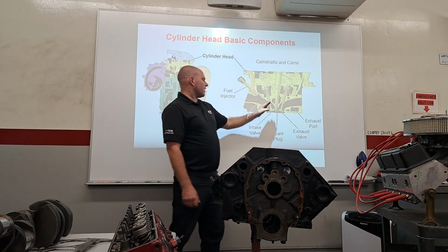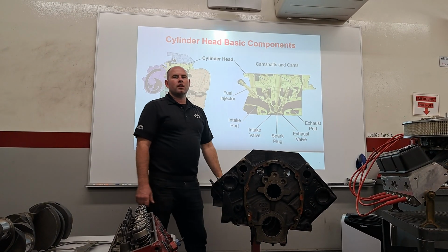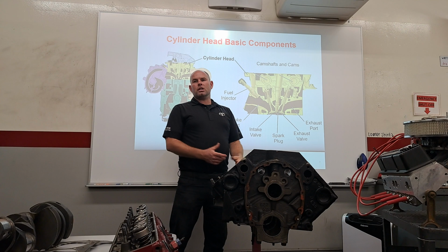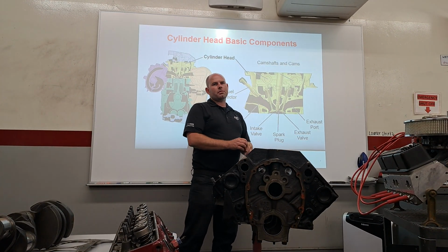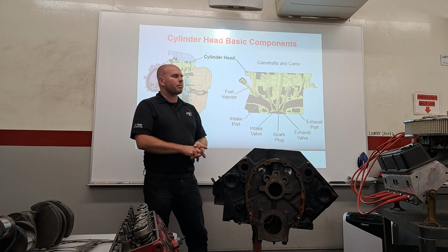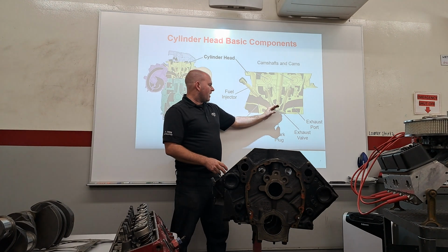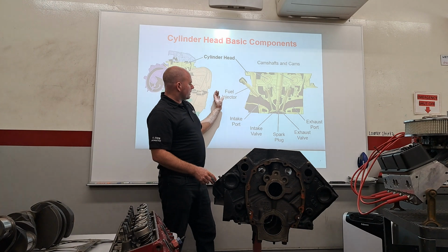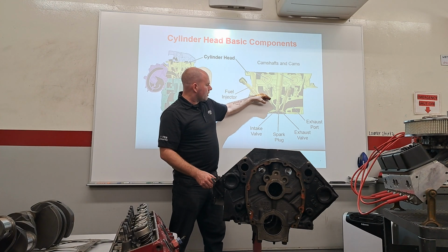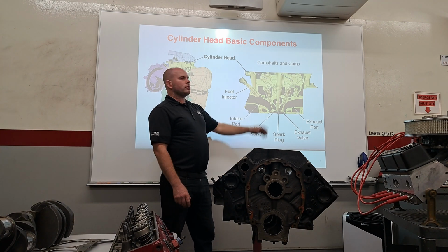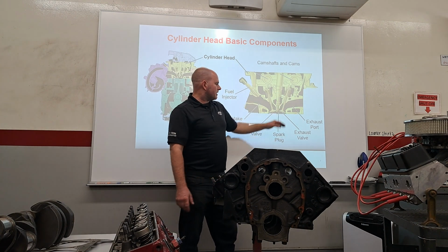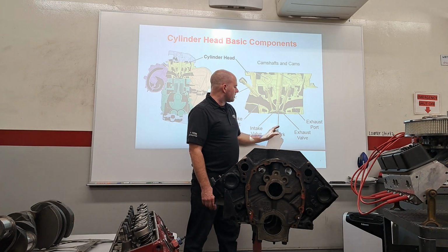All right, so from there, let's take a look. We've got an intake and an exhaust valve. They look similar. The intake valve tends to be a little bigger. The exhaust valve tends to be made of something different because it's going to get really hot. Your intake valve opening is going to allow your intake port to flow air down into the cylinder. Cool. Then we can close the exhaust valve, open up the intake valve, open up the exhaust valve and breathe out.